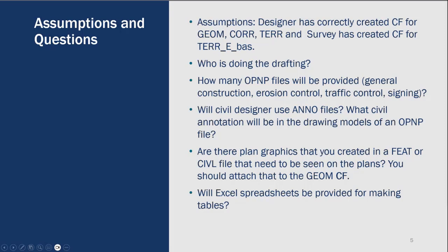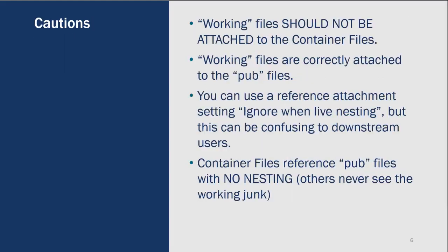So you're going to have to do a lot of communication between the designers and the drafters. Now, I have some cautions, and this comes from experience and a lot of mistakes. So be very careful if you are a designer creating those container files. Working files should not be attached to container files. Container files are our lens through which we see your published information.